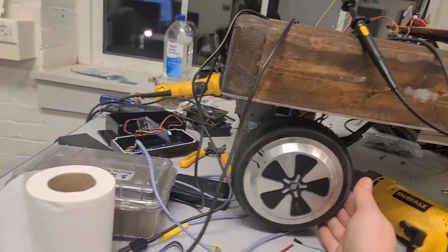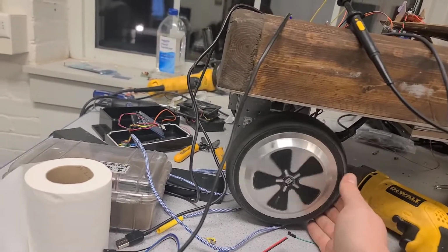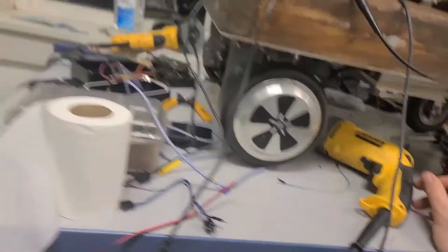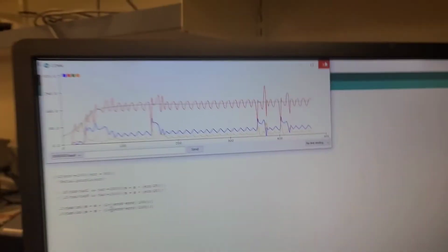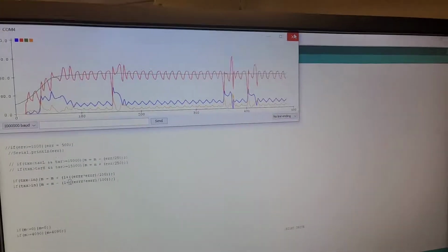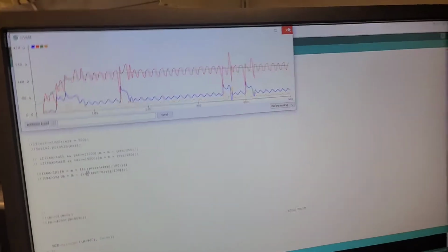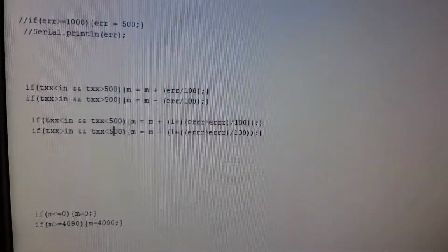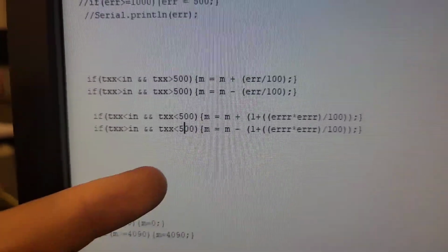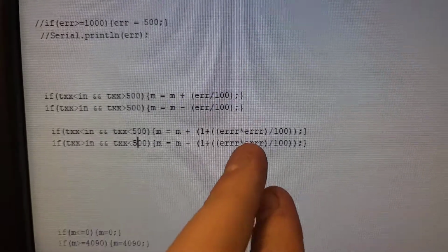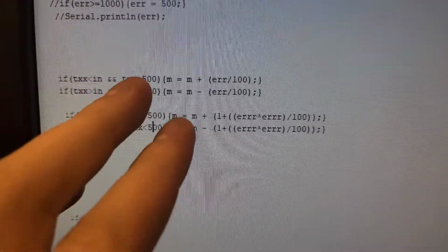Mostly you'll have clamping, and then once it starts moving or it goes over a hill or something, it won't be such an instantaneous shock to the feedback system. So cool, but it's good that it works with it anyway. All right, so I changed the feedback system so that if the wheel spins slowly, make the change rate steeper, and if the wheel's spinning very fast, no need, make it smaller.